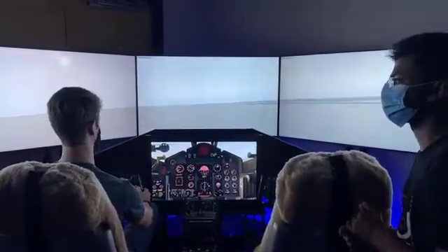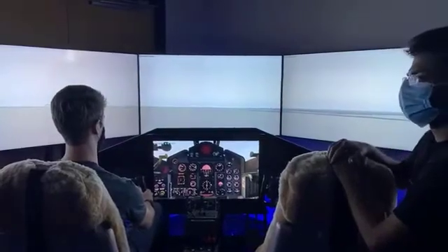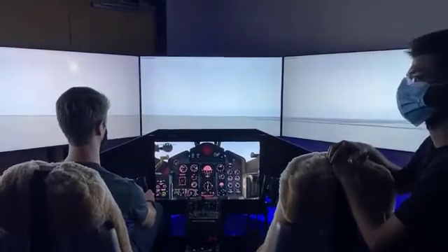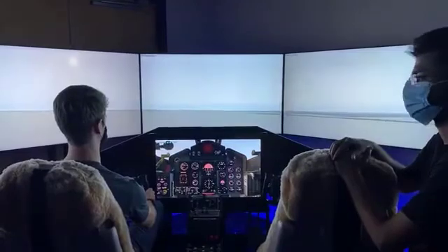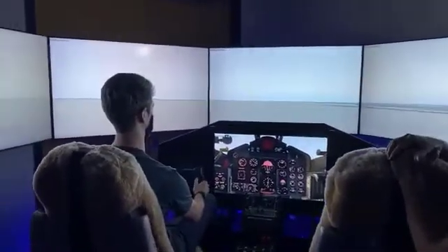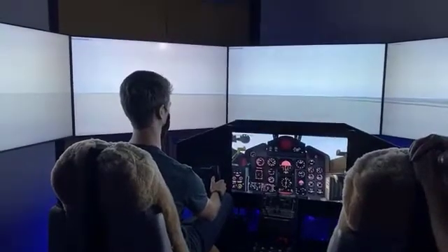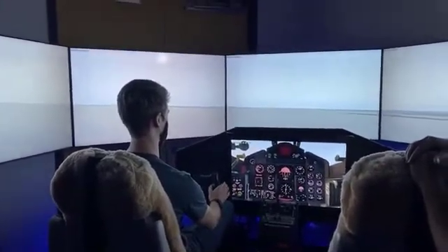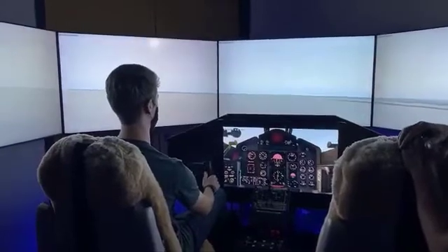So yeah, when naval aviators are landing on an aircraft, the first thing they do as soon as the wheels hit the ground is they actually go back to full power, which seems counterintuitive since you're trying to stop in a short distance, but like Bob said, that's to make sure you have a bolter, which is what they call it when you miss the cables like I just did, so you don't stall as soon as you go off the end of the runway and hit the water.